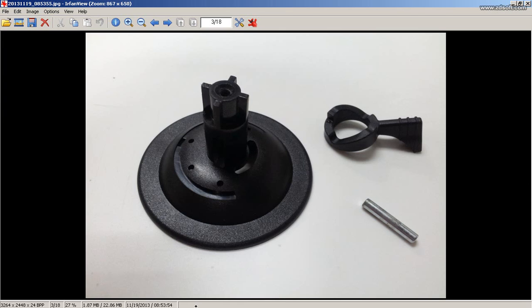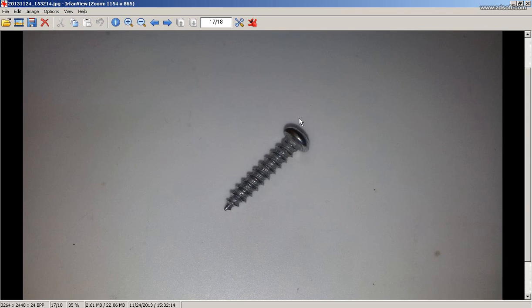Sometimes this screw is a standard component. Sometimes you can import that standard component if you use the SolidWorks library file. If you register on a website called 3D Content Central, sometimes they have certain standard components like screws, springs, and other mechanical standard components.